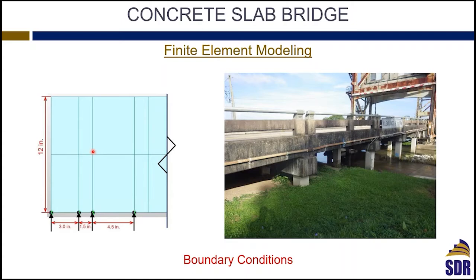If you don't know, you can end up also having moments and shears and internal forces that are not representative of reality. So we have to be very careful about boundary conditions even for new designs. When you look at our slabs here, you will see the slab spans are not supported at a specific section. They are supported over 9 inches, and they have this haunch in the slab spans. So you are actually supporting 9 inches of the slab.